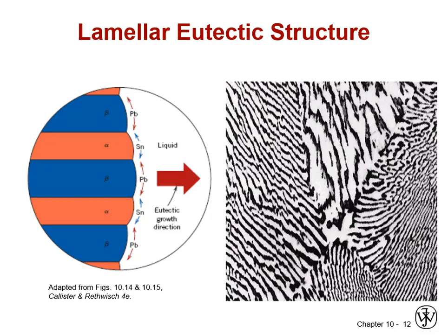Usually when we cross a temperature boundary of a very specific composition, we will have a solubility limitation drive. We'll go from a liquid where two constituents, in this case lead and tin, are both very soluble together in the liquid, but when we try to solidify them, we find that they are not at all soluble in one another.